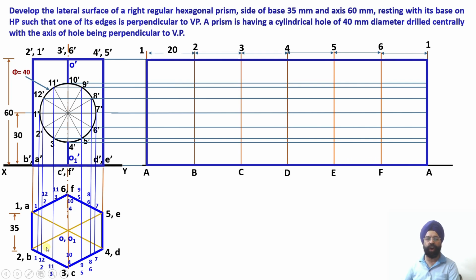So let us now draw the coordinate locations of all these 12 points from the top view and then transfer those points over here. Please see, one center point is this one, vertical edge 3C. So my circle will be distributed across this particular cross section. This is the vertical edge and these two faces. This face, 2B3C, will contain this semicircular portion of the circular hole.